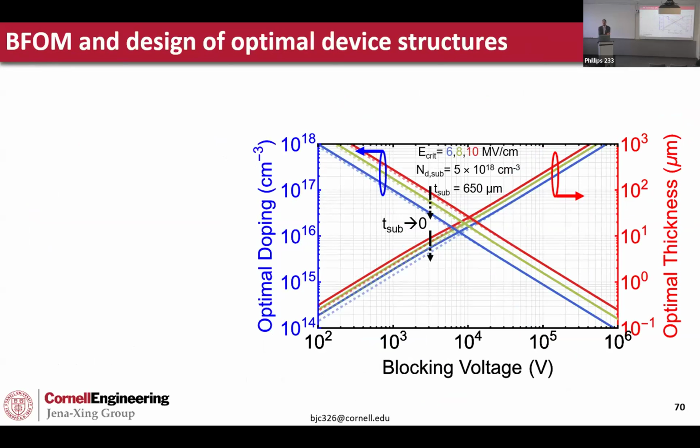Not particularly. Like I said, this plot assumes several things, vis-a-vis that we're at E crit already. And as I was showing through the earlier slides, it's hard to reach the minimum on resistance, and it's relatively hard to reach the maximum breakdown voltage. So if we had a perfectly behaving ideal device, then yes. But in our case, we're not limited by the material itself. We're limited by these intrinsic and extrinsic defects. So if we fix those, then this is, does that answer your question? Yeah.